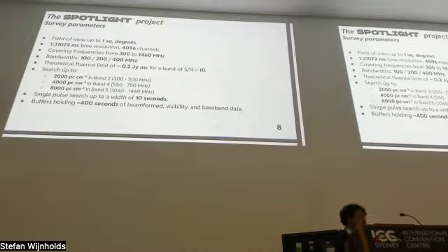So the field of view is about 1 square degree. The time resolution that we get with the system is about 1.3 milliseconds with 4096 channels. The bandwidths are 100, 200, or 400 megahertz depending on what the observer has set up, because as it is a commensal system, we will be dependent on what the system is set to by the observer. The theoretical fluence limit is about 0.2 Jansky millisecond for a signal to noise ratio of about 10.